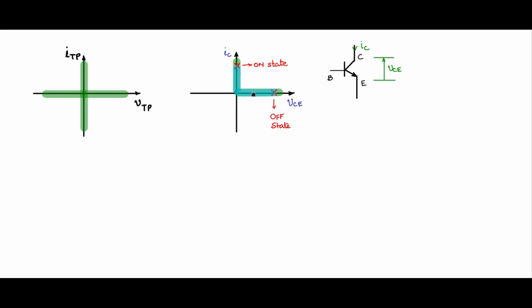In all these portions of the route current is 0, and then once 0 voltage is reached, in all this portion of the route voltage is 0. So therefore in transiting from the off state to the on state, you do not lose any power. Likewise, while coming back, you also do not lose power if you are using this route. So in this route, you have 0 switching losses.